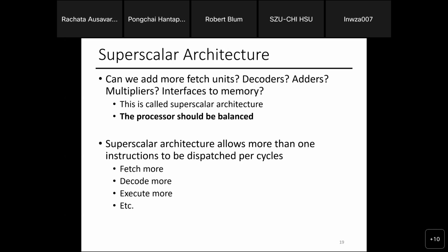That window is already ordered. So you know what you have to finish. So the entry in that window, even when you dispatch to the ALU, you keep the entry and you only delete the entry when you're done. That way you have the order in the window, and all write back does is look at that window at the end and ask, are you done? Oh, done. I retire. Go to the next one.